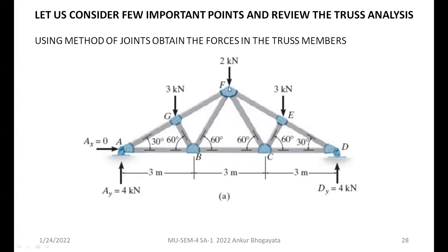So you can simply write a statement that due to the symmetry in geometry as well as in loading, the forces are the same. To say that, you need to have symmetry in both the geometry and the load. Otherwise, you should not go for that statement. So once you notice that your geometry is symmetrical and your loading is symmetrical, you can do half the work, and then you can mention that due to the symmetry of geometry, the forces are the same. So then you can tabulate all the forces. Let us say 6 plus 6, 12 forces.